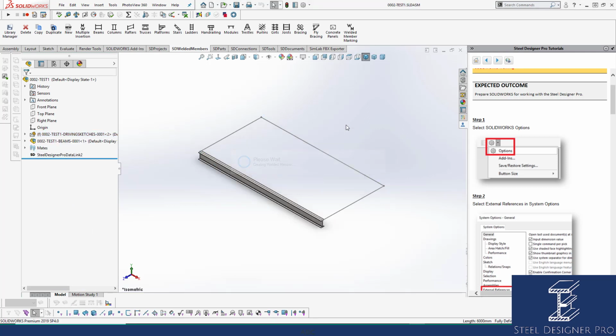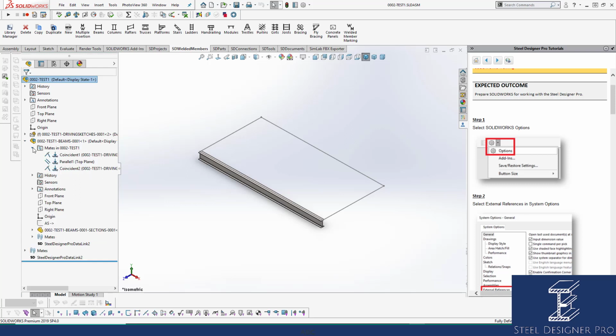Now when I say insert it on this sketch segment, there's a few things that have occurred for that to happen. So let's go through the process and break it so that what's in it starts from scratch. So at the moment, we have not connected this member to anything. Right? And inside of it, it uses mates to lock it into place, and it uses a relationship to a sketch segment that we put inside that drives it.